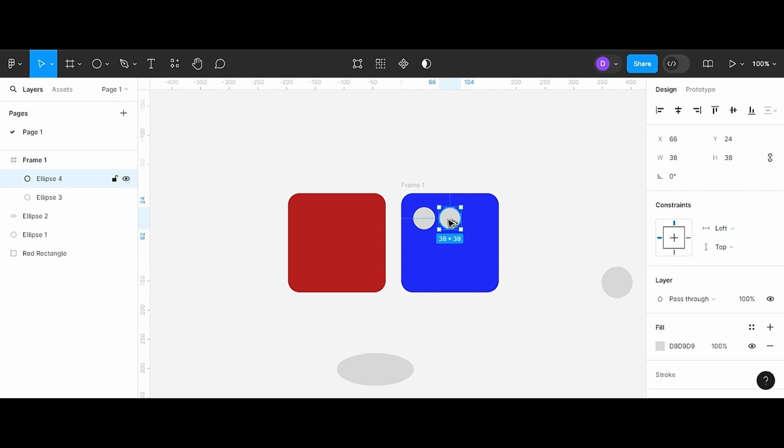So when you hold down the Alt key, you see this arrow like it's doubled. Now when I release the Alt key, you have a single arrow. When I hold down the Alt key, you'll be seeing the double arrow. So once you're seeing that, you know the Alt key is activated and you can drag out. So when you drag out, you have a duplicate of that item.